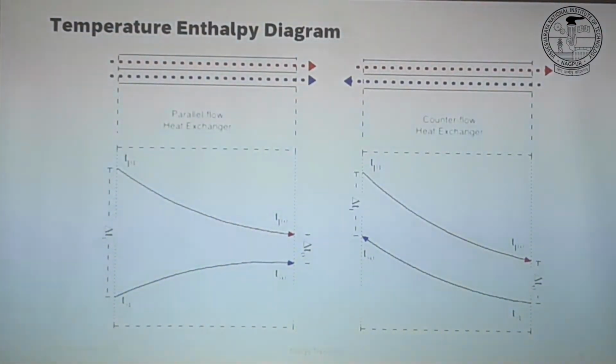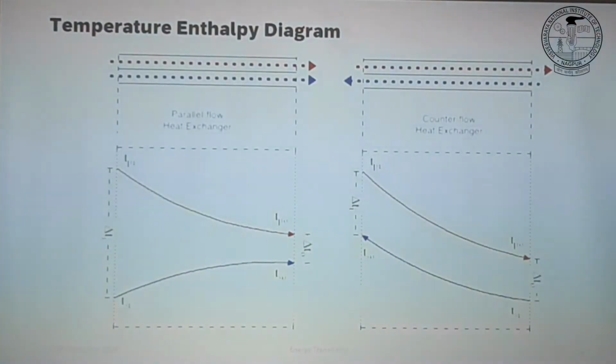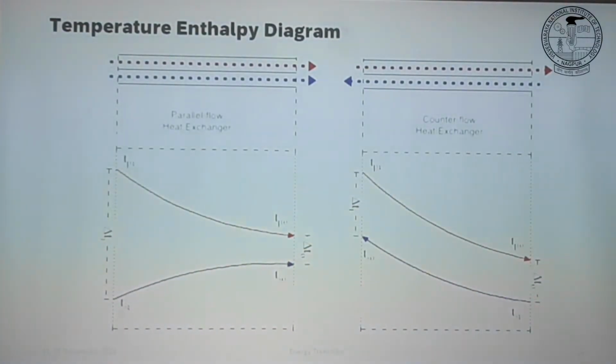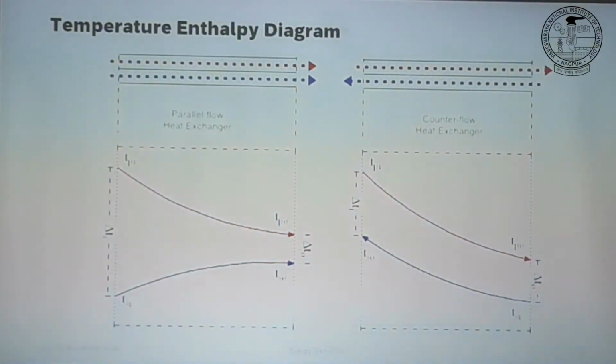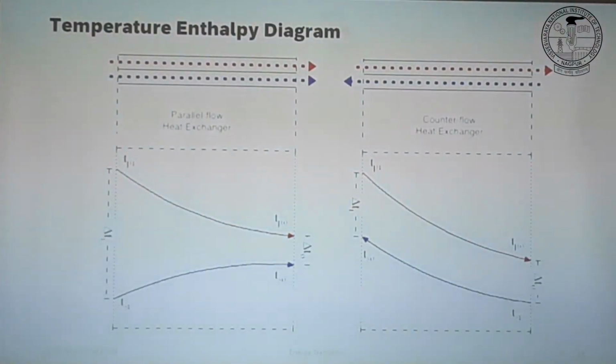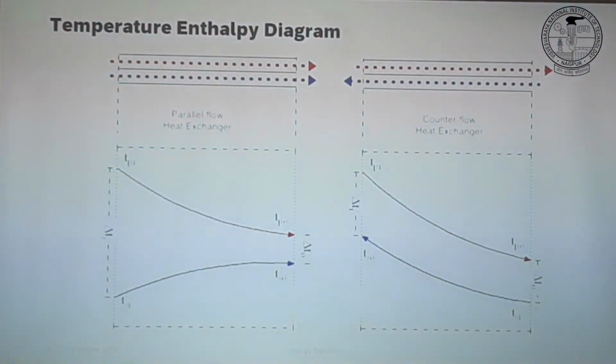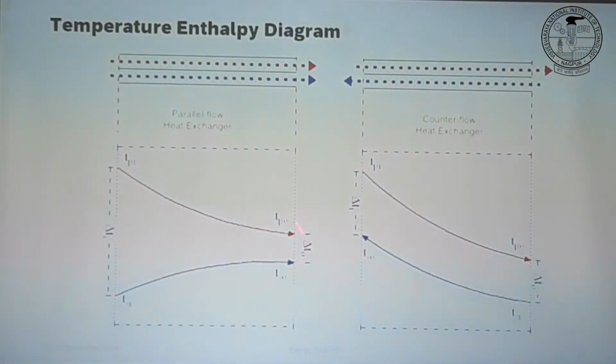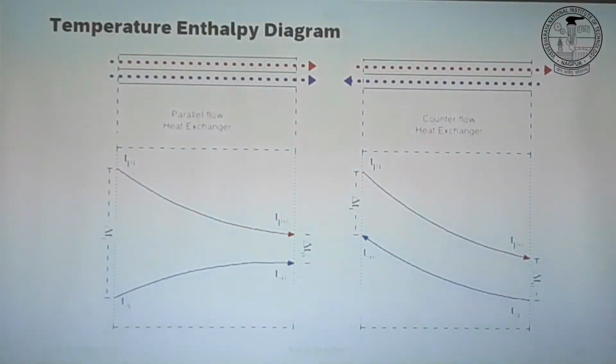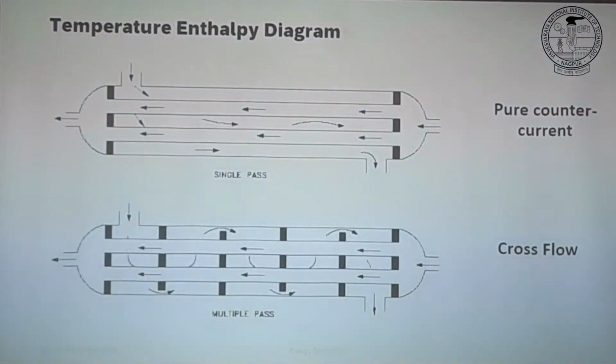You have 850 reformed gas or product gas with very high CO, and you want to have the cold side seeing this temperature. If you put the hot side on this side, meaning counter current, your metal temperature will be higher. So although people think that since LMTD is higher, we just take this one, there are some distinctive advantages of co-current as well.